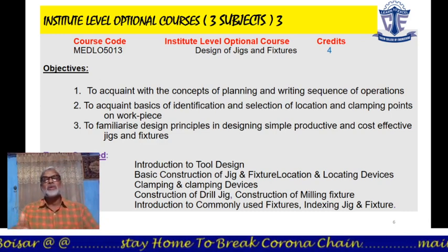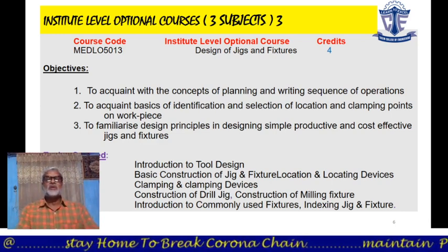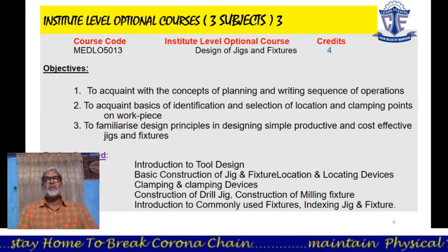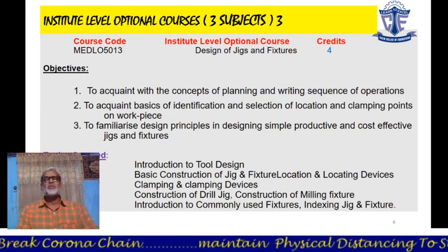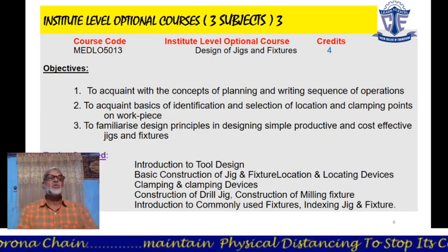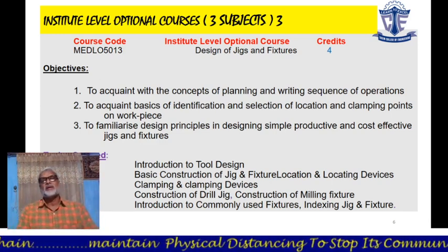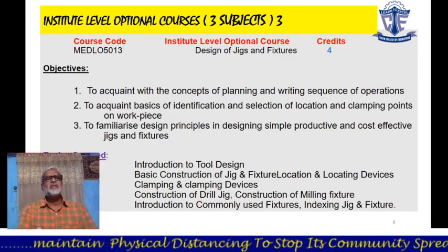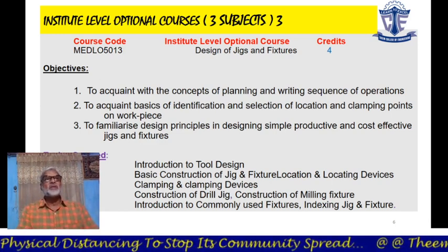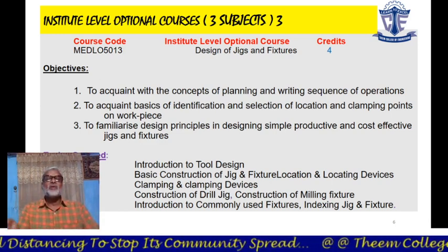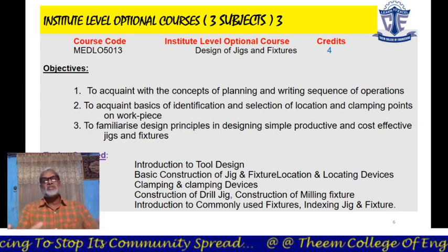Because to get higher production, jigs are required, fixture locations are required for fast locating, and locating devices are required. Jigs and fixtures are the ones which immediately hold the product for machining. And in a locating device, you just keep it and it gets located. Locating device, clamping, unclamping device is automatic, mechanically or by gravity or by sensing devices.